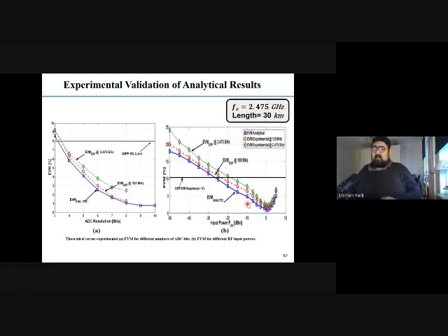So this is just a comparison, because we have a concept of undersampling in digital radio over fiber from digital signal processing. DSP is just undersampling, so that you have images of the carrier frequency. If you have a 2.4 gigahertz carrier, you can undersample it by using the band pass sampling concept. I will not go into detail of band pass sampling because it's just images of the system that you have. Generally you see the channel and you say that the carrier should be greater than 2 times the fs. But actually there is the other side of the equation as well that is generally ignored, and we don't see that. So that is the undersampling or bandpass sampling part.